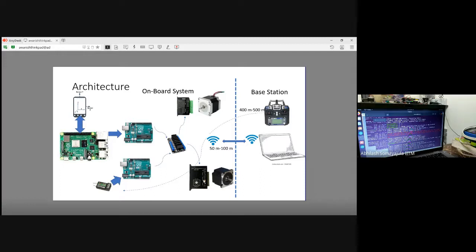For example, if this motor is sensorless, we do not have a sensor. It's still a BLDC motor, but we define the input on the PWM, the ESC, the electronic speed controller, the small ones. It takes that input as a PWM, converts it into trapezoidal form, and then accordingly it runs.